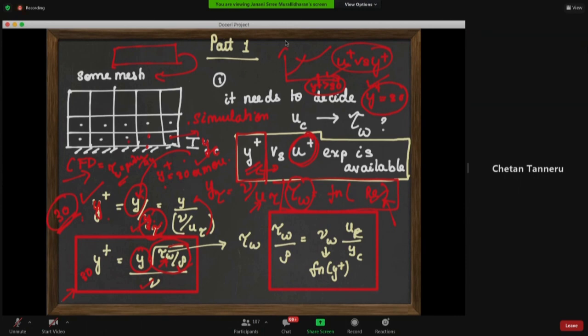Ma'am, a couple of minutes ago, you mentioned y plus being calculated from the wall shear stress. So over there, that relation is used to calculate y, no, ma'am? So y plus, you had experimentally concluded that it is around 30 for the turbulence models. So I don't understand the y plus calculation from tau w. Okay, there are certain layers which we'll have to get into.